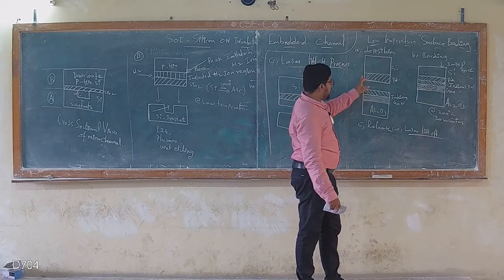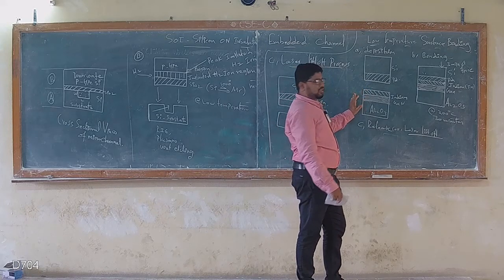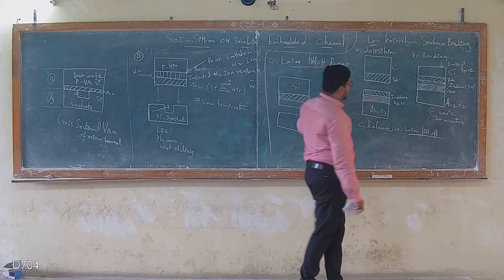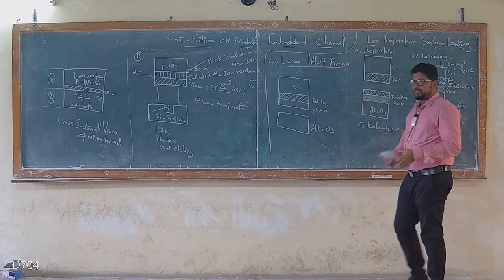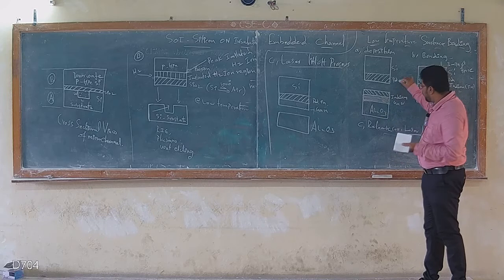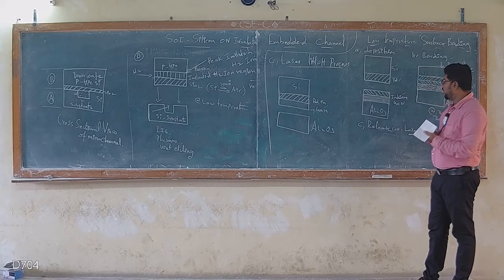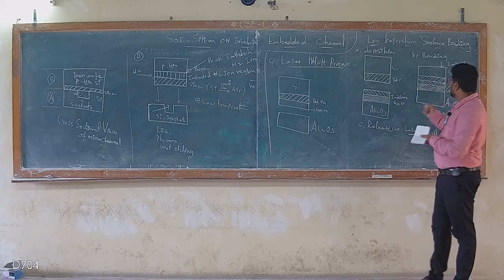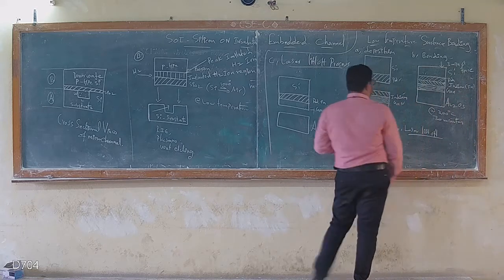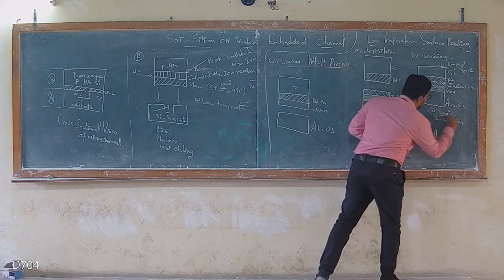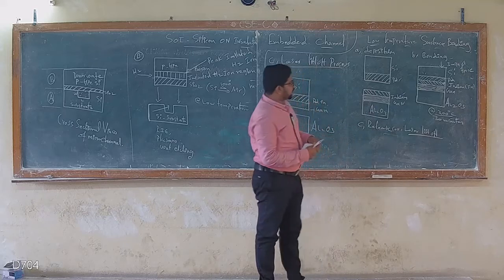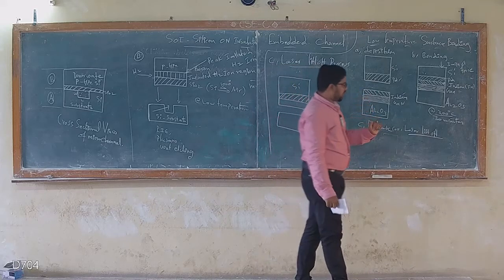Both can be done in a CVD or PVD process, using either thermal evaporation or sputtering. We have coated palladium and indium over the silicon as well as the gallium arsenide. Stage 2 is called bonding. It happens only at 200 degrees Celsius, which is why we call it low temperature surface bonding.